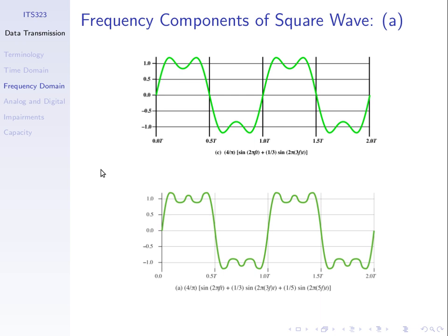Here's our first signal. What's the frequency of the first component? These are the things you'll answer in the quiz. What's the frequency of the first component in this signal? 1,000 hertz, because of the general form of 2 pi f t. With 2,000 pi t, this would be 1,000 hertz for this component, and the second component, 3,000 hertz.